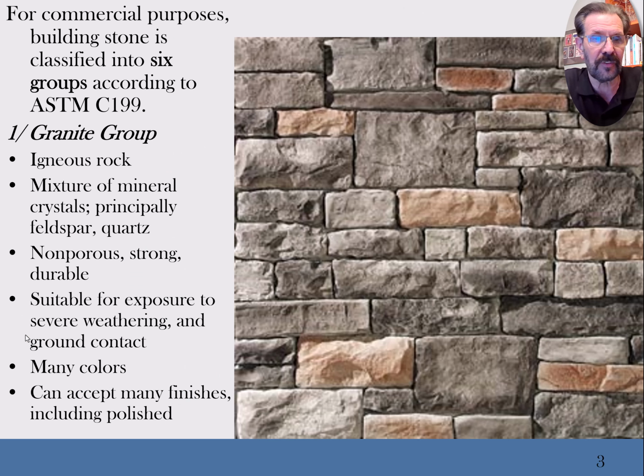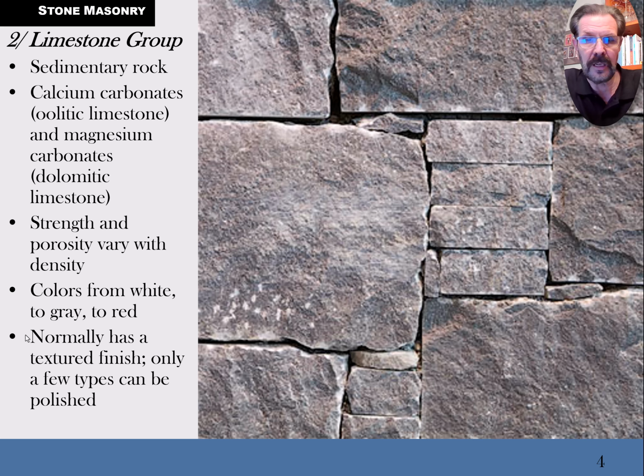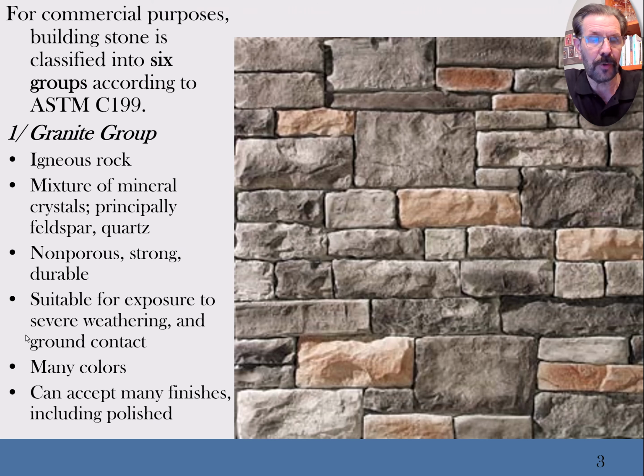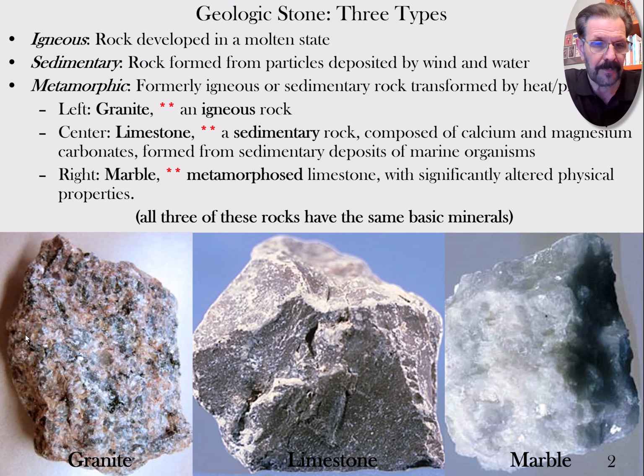So I'm just giving some examples of the granite group, the limestone group here. Let me back up for a minute and just point out that granite is not anywhere near as porous as limestone. Limestone is more porous. It's going to be sedimentary material, so water can soak in through it more. So you wouldn't want to use limestone or shale as a countertop because it's so porous. You'd have to really heavily seal the material with some kind of a synthetic sealer.